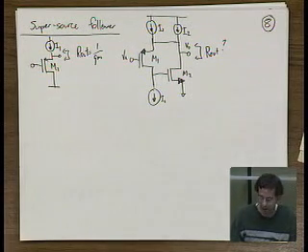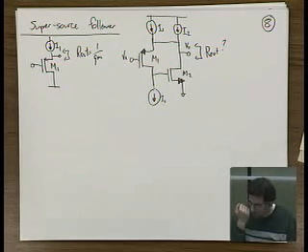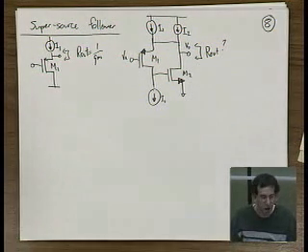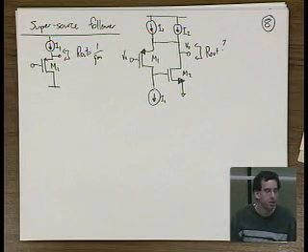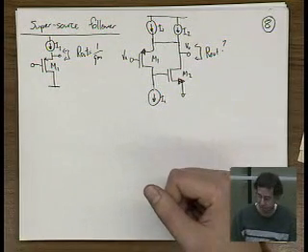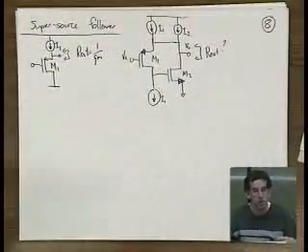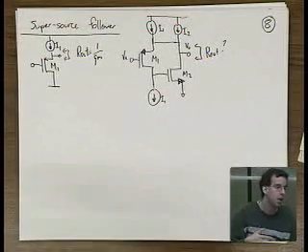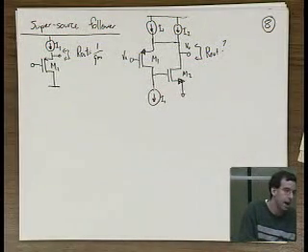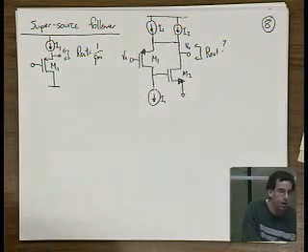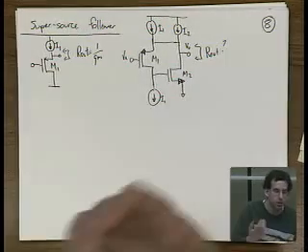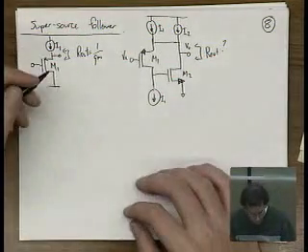All right, I'll walk you through it. One way to try to figure it out is to redraw it in a form that fits into one of these networks. Then when you redraw it, you'll see whether you're feeding back a shunt feedback quantity, which means you're feeding back a current, and so on and so forth. So let's just start redrawing it.